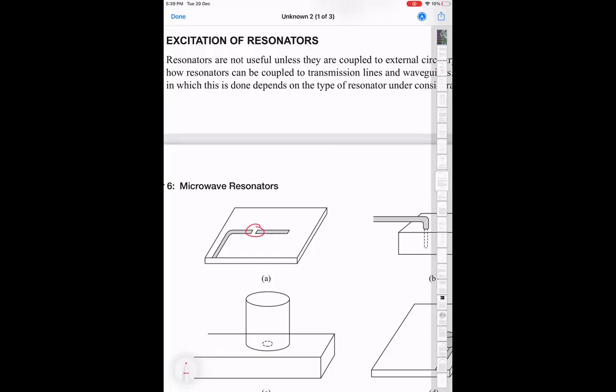So this is an example of this rectangular waveguide. Of course, we need a way to get into it. Otherwise, first of all, machining something which is completely hollow on the inside is impossible. So we make it in two pieces, and then we just close them together. So once they are closed tightly, then inside you have a closed volume. These two dimensions, this dimension and the dimension coming out this way, those are the two relevant dimensions for the TE mode. So remember it said TE101. So the 01 is the shortest dimension.